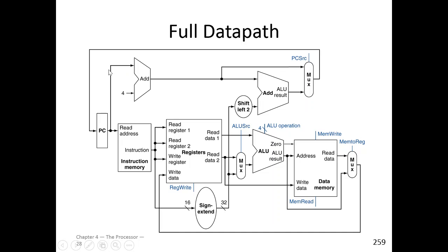Every instruction, except for branches, a control path change, is going to increment by 4. So we add this additional data path up here that increments the PC by 4 every time. If a branch or a jump was happening, it might further change the next address, and then it writes it into the PC. But for R, load, and store words, I already showed those paths.